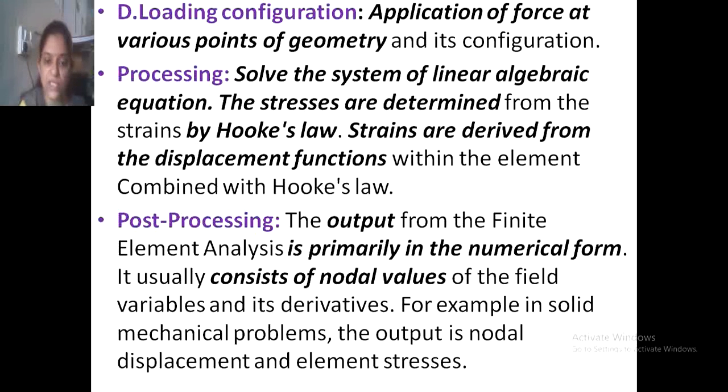It usually consists of nodal values of the field variables and their derivatives. For example, in solid mechanics problems, the output is nodal displacement and element stresses.